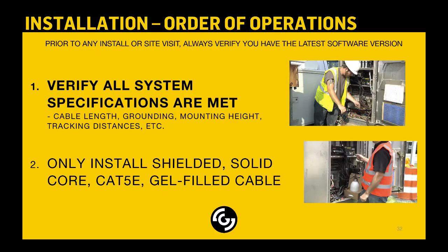There's also on the support site, well, actually, I'll get into this in just a minute, so I'll hold off on what I was going to say. You know, checking the cable length, the grounding, the mounting height, tracking distance, all of these things are a part of our specification. Verify that those are meeting the specification.